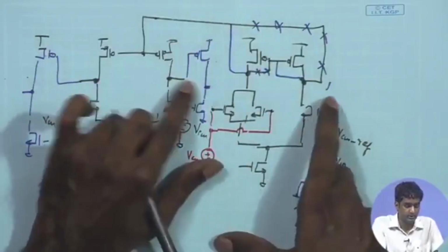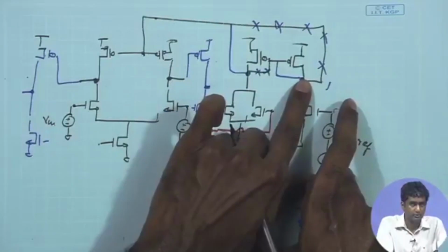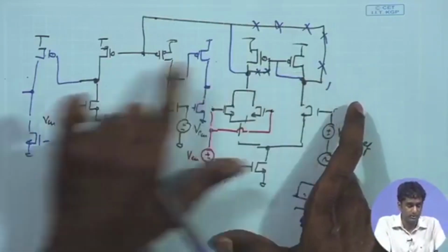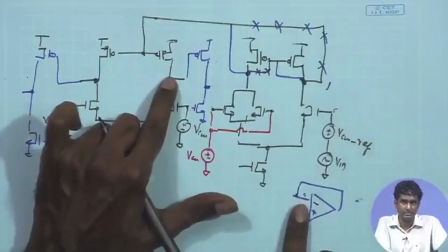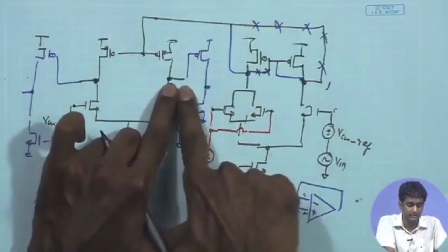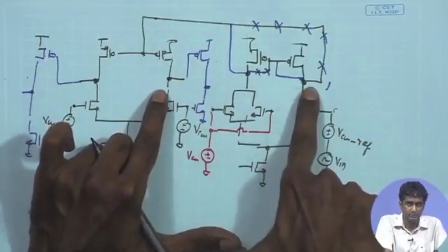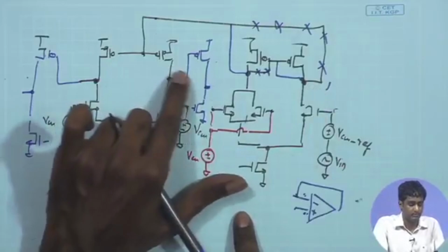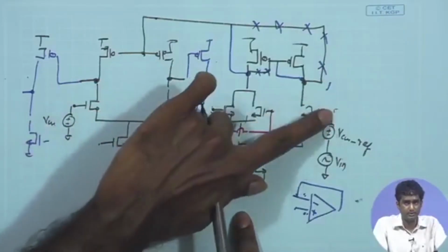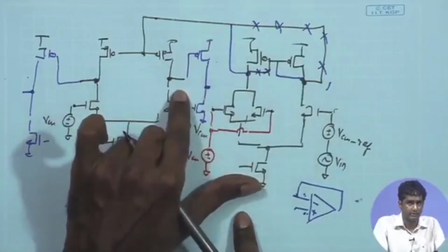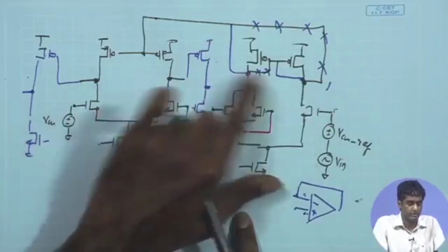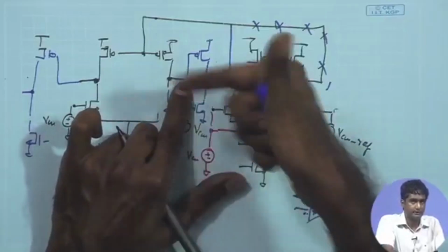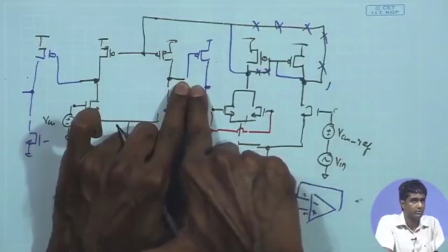That will basically introduce the Miller effect here strongly. So that will give a large effective Miller multiplied capacitance over here, but you don't want that Miller multiplied capacitance over here, because in the closed loop, that capacitance also comes between this point and this point, and we have a signal path from here. So we discussed, let us have a buffer and then connect the capacitor between this point and the buffer output at the first stage, so that the buffer output has low impedance. Even if there is a Miller effect coming over there, it will not affect.